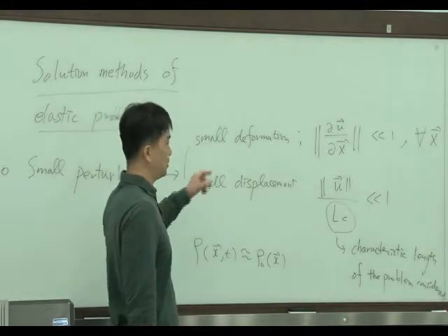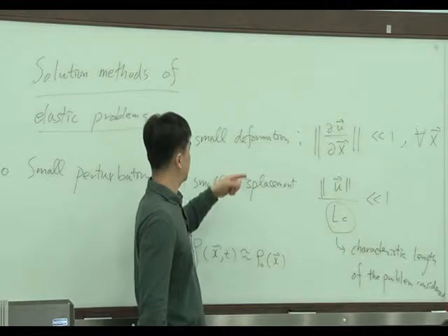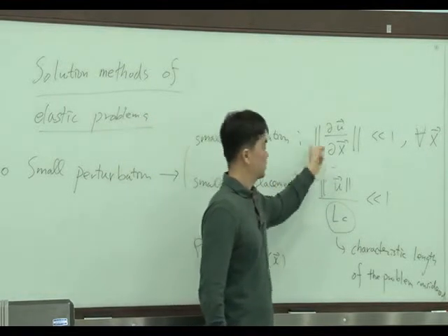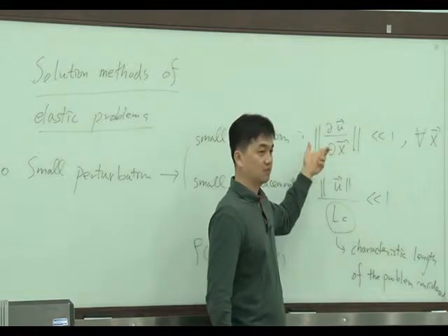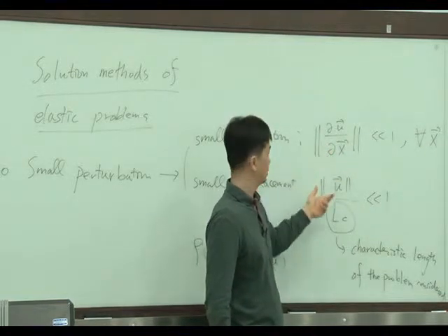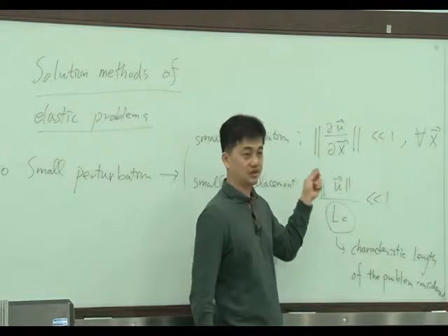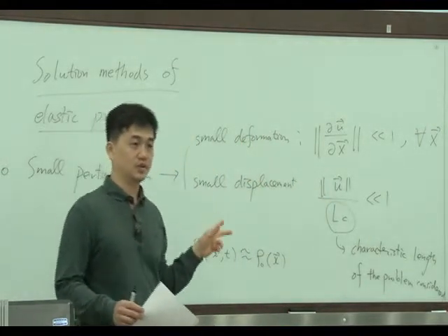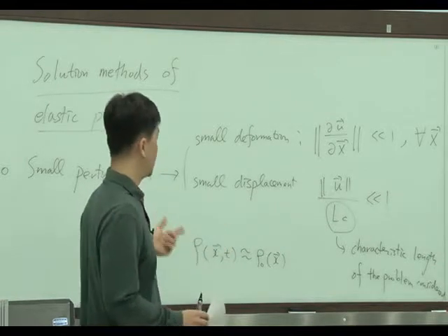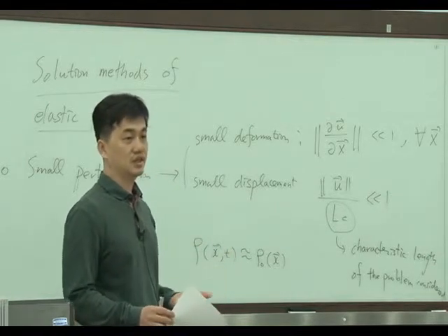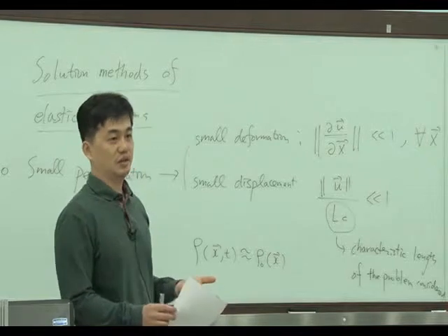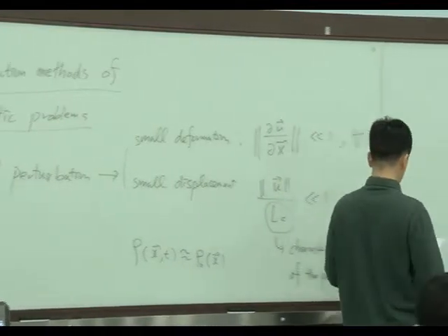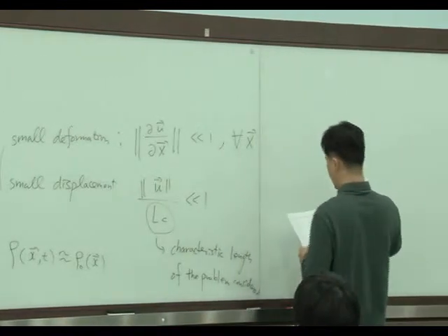So now I think you understand the small difference between deformation and displacement. Okay? Deformation is a gradient of displacement. Displacement is just displacement, difference between positions, right? And the measure of deformation is what? Strain, right? Okay, so now let's summarize the governing equation.